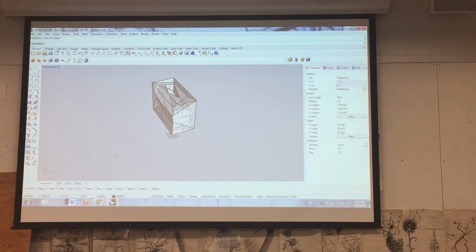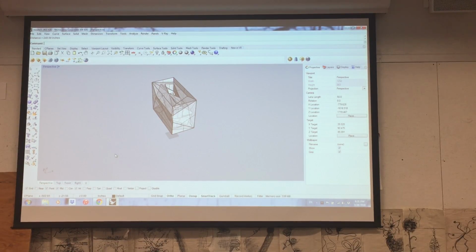That's only the scale factor for 1/4 inch. Okay? What would the scale factor be for 1/8 inch? 96. Does that make sense? We multiply this by 8 to get 1 inch, and then we multiply it by 12 to get 1 foot. So if you wanted to write that out, it would be 1 times 8 times 12, 96, right?